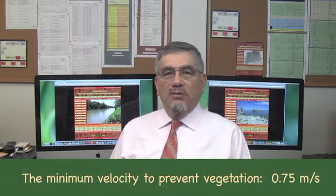The minimum velocity to prevent the growth of vegetation is 0.75 meters per second. For most applications, the design velocity is kept below critical, that is, below a Froude number equal to 1. This limits the design velocity to a practicable maximum.